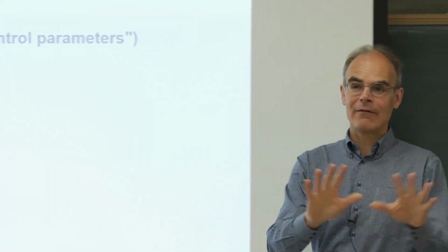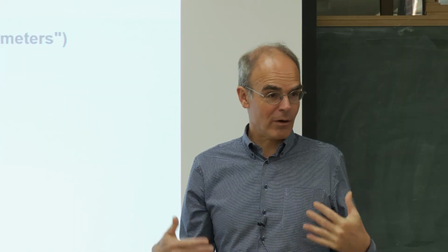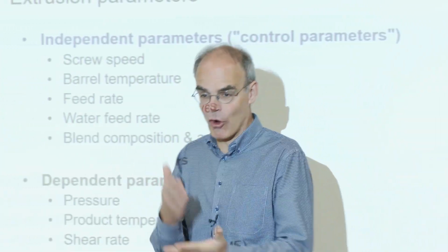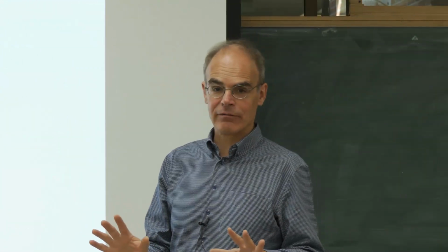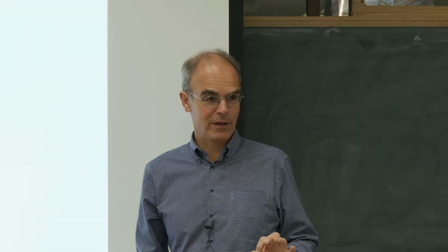I have certainly not seen any significant issues around extrusion with people getting harmed. But always be careful. It's hot, under pressure, with power, with everything. So really be careful. And if the pressure goes up, shut down, if you don't control it.